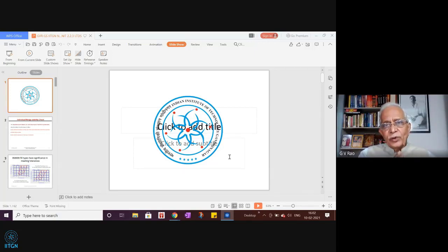That means before we buy it now, along with the bid which the manufacturer is going to give to us, we should see what the manufacturer's roll values actually are, the MARV values. And in fact, nowadays, each roll or each lot sometimes comes with a certification that this is how the test is done. One can get more data on this also. So more data means the full stress-strain curve also is available, and this is how we certify the material is going to be suitable or proper now. So that is the most important thing which is coming out of it now.